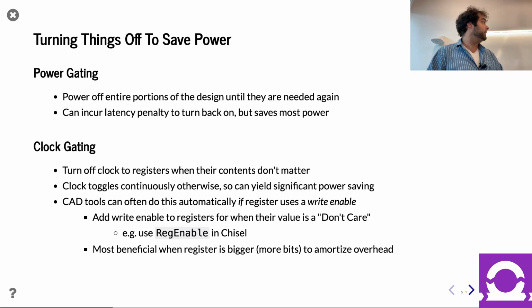When it comes to clock gating, the emphasis is on registers. And the reason why is that logic gates in typical CMOS don't take clocks, right? If you can clock gate, the registers won't change your outputs. And if your outputs aren't changing, the logic downstream of these registers also will not change, right? So you're reducing their activity too. You only need to control the clock going to the register for the same impact.